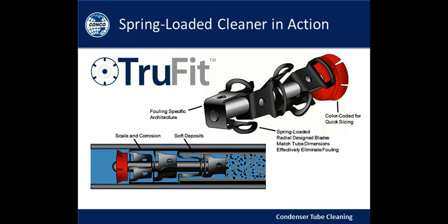Now, your condenser tubes came with a specification. They are sized, so they give you an OD diameter, and they give you a wall thickness and a tube length. And this is fairly straightforward. In fact, one of the event downloads is the Heat Exchanger Institute, HEI, data sheet. That data sheet is a blank form, but you should have one of those for each one of your condensers or heat exchangers in the plant. That will provide you with the information that you need. So,